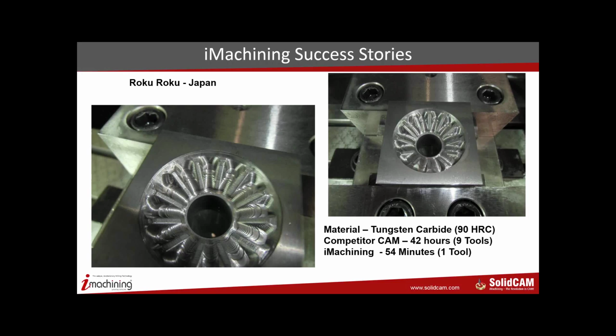The last one was very important, and that is to determine the machinability of the material. If you can get the machinability of the material right, you can actually surpass the tool life suggested by even us. You can get extremely accurate cutting conditions, and overall your process will be much faster and smoother than what would have happened if you had just believed only the UTS and gone ahead and machined it.